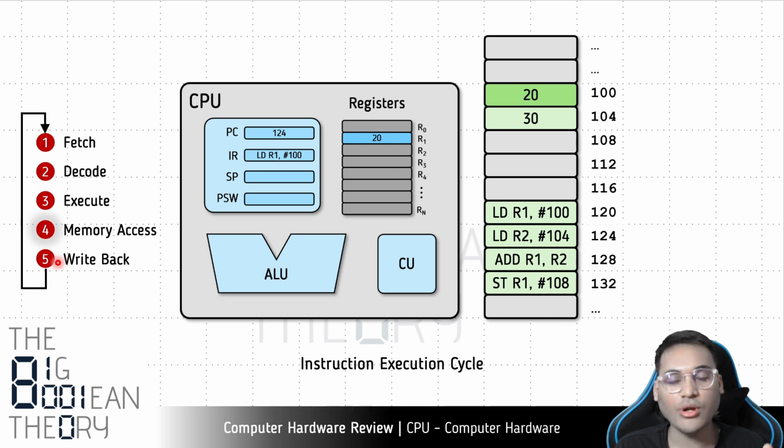The important point is that there are certain instructions, like data movement, where execution and write back are not required and only memory access is done, so these two steps will be skipped. Whereas there are certain instructions where we combine two values in the execute step, and whatever new result is produced, we write back into the register file, or the general purpose registers. So this is the load instruction. Again, the write back step will be skipped, and this completes the execution of our first instruction.